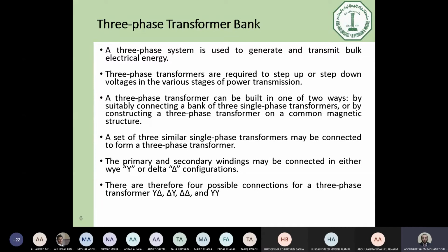Industrial loads may need relatively high voltage, maybe 12 kilovolt for instance, and after that, the distribution transformers which are very close to your home, you will find these transformers around 6 kilovolt to 0.4 kilovolt. So we step down the voltage in many steps according to the loads that we are going to connect through substations and distribution transformers that exist close to your homes.